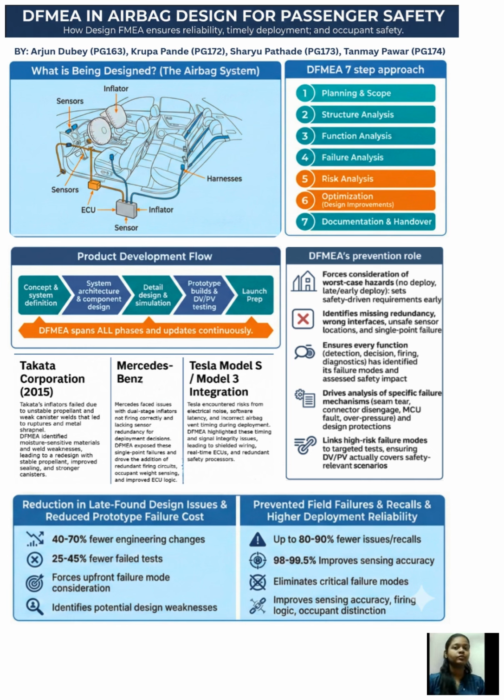Real-world examples also prove it. Mercedes-Benz once struggled with deploying airbags on rough roads. DFMEA helped redesign their sensing logic and eliminate this failure. And also, Toyota once faced a critical issue of airbags not deploying on angled collisions. They used DFMEA-driven crash pulse analysis to redesign thresholds and expand their algorithm's recognition range, thus improving their deployment consistency. In short, DFMEA transforms airbags from hoping they work to knowing they work. It eliminates critical failure modes, prevents recalls, and makes every deployment safer, smarter, and faster for the passenger.